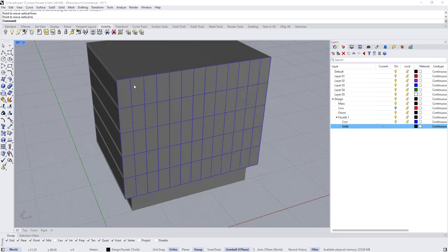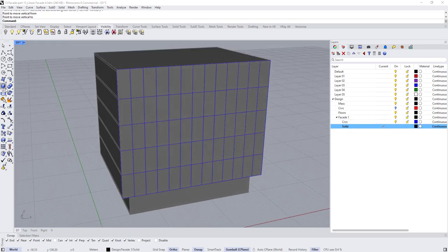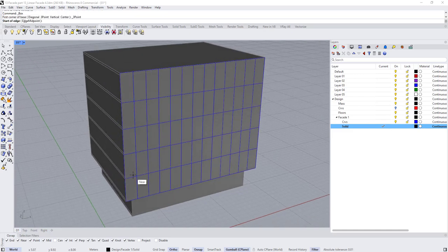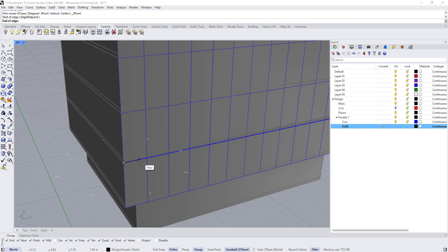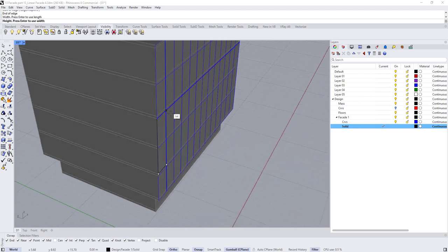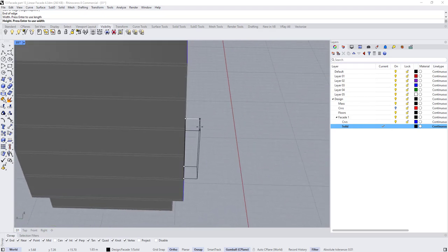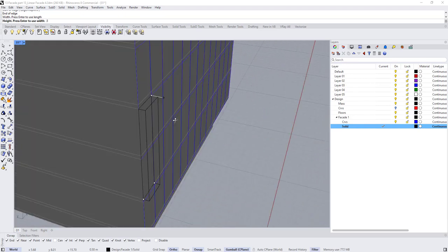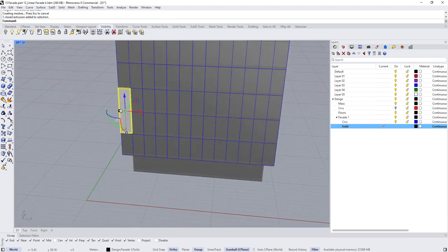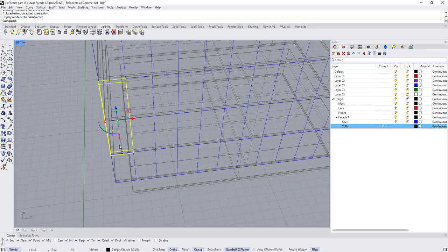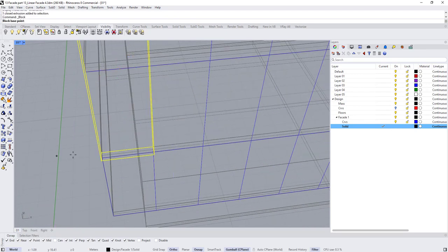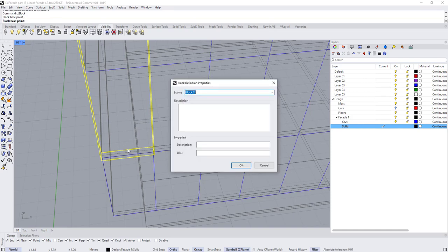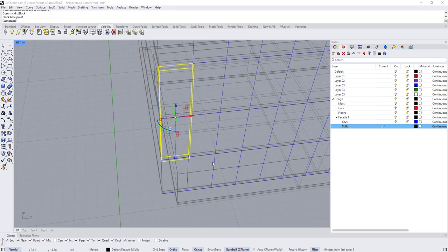Now let's select the solid layer, and I'm going now to start creating blocks. So let's choose 3-point box. So for this part, from here to here, I'm going to use one block, but let's set it from here to here. And it's going to be 0.5 meter maybe. Maybe less than, maybe 0.4 would be fine. Yeah. It's going to be the first block, switch to wireframe, selected, go to define a block, snap to the midpoint, and name it B1.